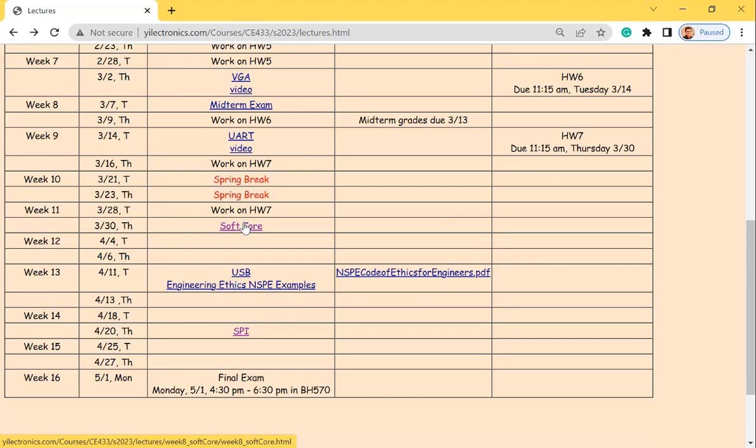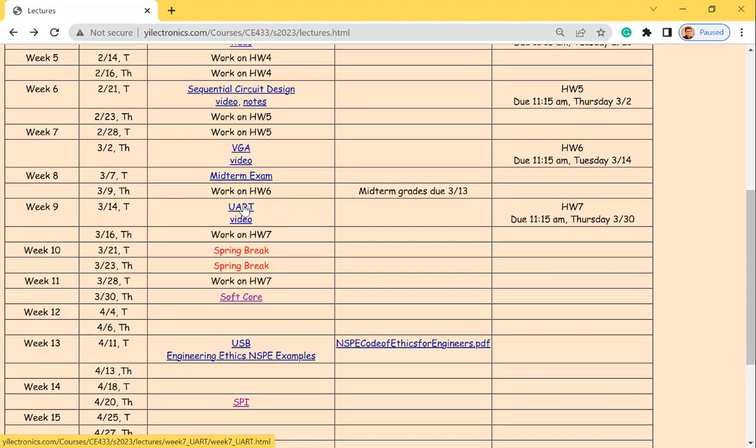Your microcontroller will have an SPI port, and if you put a UART in it, it becomes a microcontroller with a UART in it. So it's not just a microcontroller with all the digital GPIOs, the general purpose IOs, but also some more advanced serial communication ports that it can directly use. It's just adding more features to it. That's why when you open up the data sheet for the microcontroller, it tells you that this microcontroller has I2C, SPI, ADCs, and PLLs, and all kinds of features, trying to make it look good, right? Or it's more versatile because the customers need it.